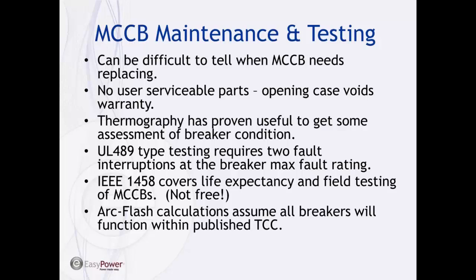When we get into Arc-Flash analysis, we find a lot of parts of our system depend on a molded case circuit breaker operating upstream. And so it places more emphasis on breaker maintenance and testing. You go to a lot of old facilities, you test the breaker, it's not functional because it hasn't been operated in 20 years and it's no longer capable of opening.